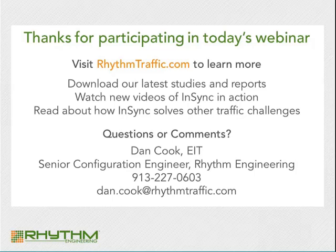How does one analyze and report existing conditions, LOS, with InSync? What software exists for public engineers and private consultants to analyze how things are working with InSync and determine how well things will work with growth or development? InSync can interface with VSIM, a simulation software. We've done that a few times, and the benefit is you can set up a really nice simulation, and then have the plugin to run InSync to monitor the traffic and control the lights. With VSIM, you can have nice reports showing total intersection delays, network delay, and level of service. You can also change your volumes to meet 30 years down the road to see how InSync will deal with traffic then.